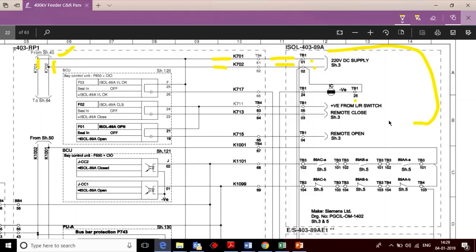When you are closing and opening the door of the isolator magnetic box, at the corner the dressing of the wire gets cut by opening many times. This happens there, because personally I have seen these things, okay. So when the positive and negative came here, you have already found that there is a problem in the circuit of the isolator itself.